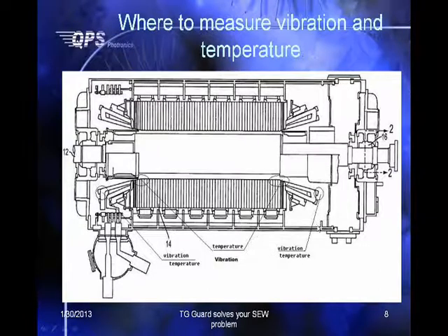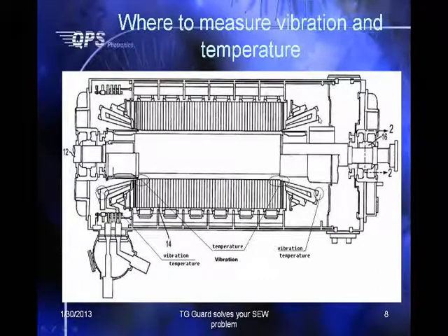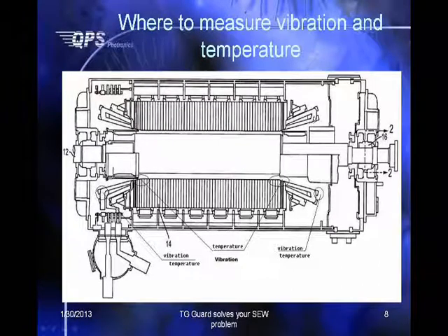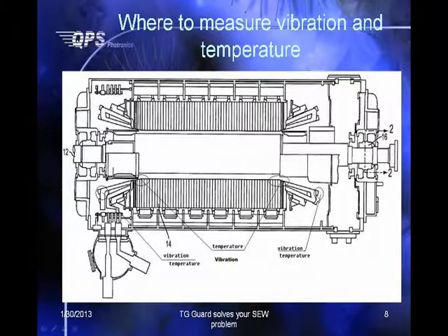Just to remind you, we're talking about 6 sensors on each end, so the minimum configuration will be 12 sensors. If the end winding has a well-defined end cap, then you can capture both tangential and radial directions. Today, in the reference site that we will show you, unfortunately, the end winding will be cylindrical. So I'm going to explain to you how we tackle the problem.